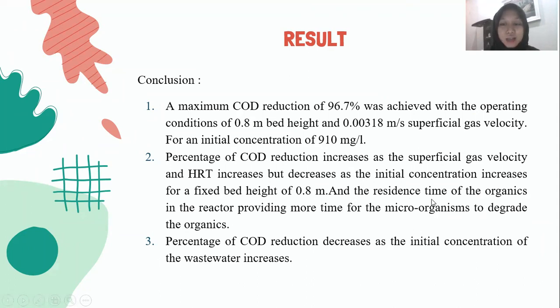And the residence time of the organics in the reactor is increased, providing more time for the microorganisms to degrade the organics. Number 3, percentage of COD reduction decreased as the initial concentration of wastewater increased.